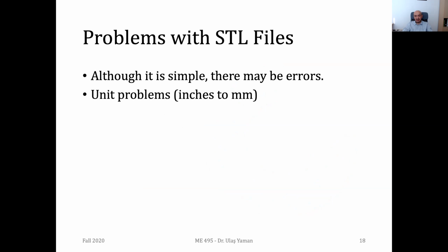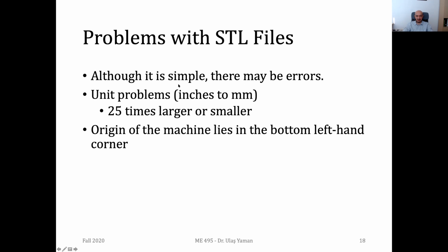We know that they are quite simple, but still there might be problems. First of all, you already know that we don't have any units for the STL files. Depending on the type of software you are using, they may consider the STL file in millimeters, inches, sometimes meters. So you should be careful about it. For instance, if you make a mistake between inches and millimeters, then your part might be 25 times larger, or depending on your conversion, it might be 25 times smaller.